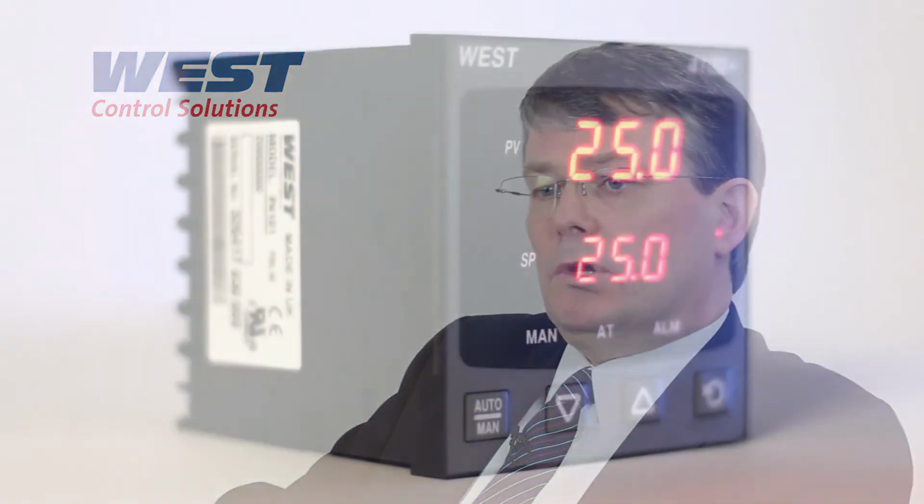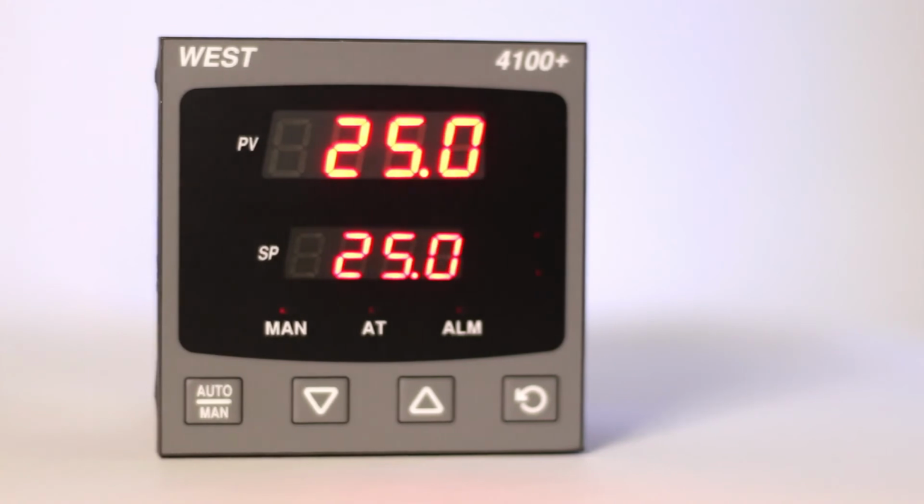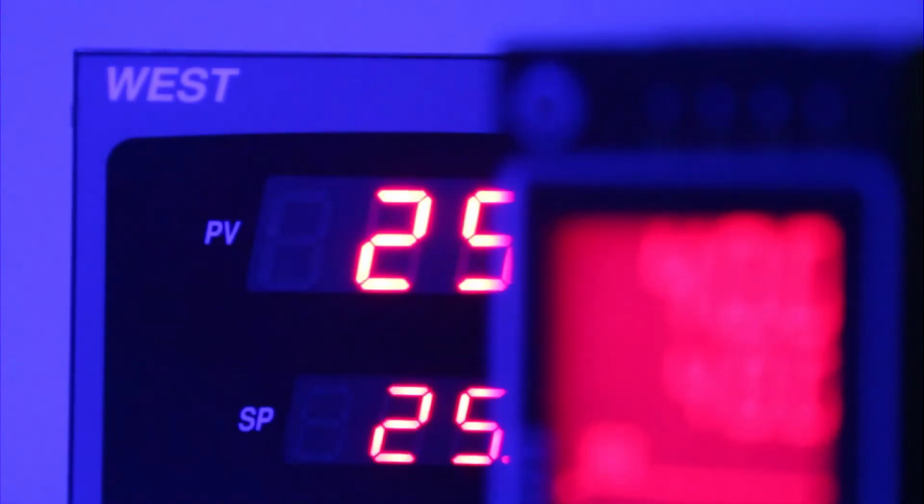So if PID is the best form of control, why would you use PI, PD or proportional-only control? Some processes do not need the additional complication of a three-term PID controller, and it's possible that the integral and derivative functions can adversely affect the control in some cases. For example, derivative is known to cause premature wear in modulating valves. This is due to the excessive numbers of small movements in the valve due to the reaction of derivative to noise in the signal. In this case, the use of a PI controller is recommended.